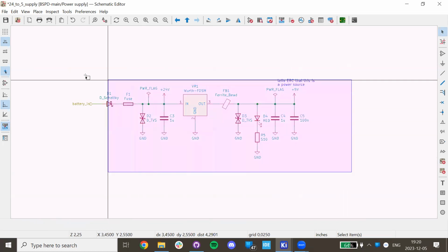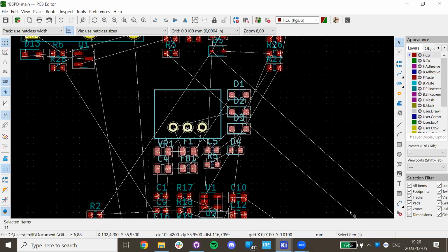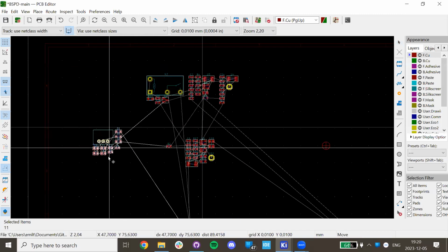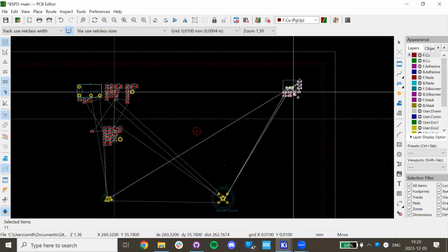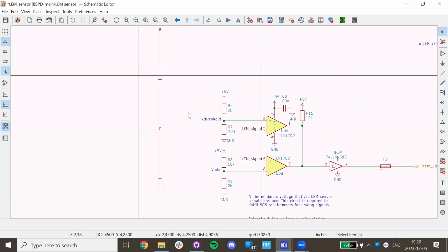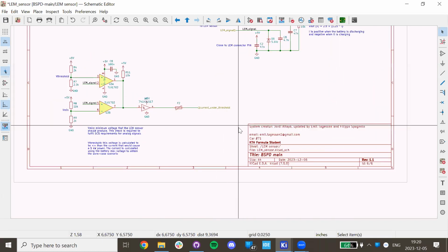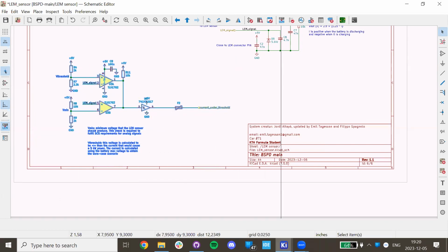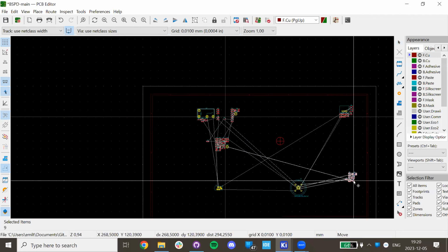Yes, so what I like to do, I just highlight all of this, even the text, because the only things that are in here, now they're linked. So now you see that all of these are highlighted. So boom, now I have all these power blocks separated, and I know I want to keep them together. So I will just grab a corner up here and I'll put them there. Now I will go back and I will grab this thing, the LEM sensor. Okay. I now know that these all should be close because you have made a function of your PCB, so you should know what relates to each other. So these all things group together, I'll put them down here.